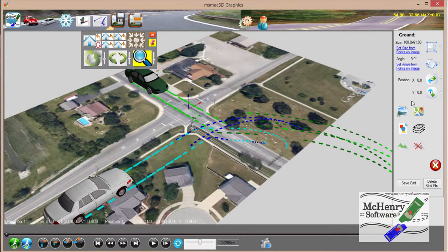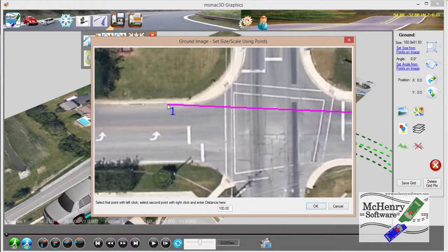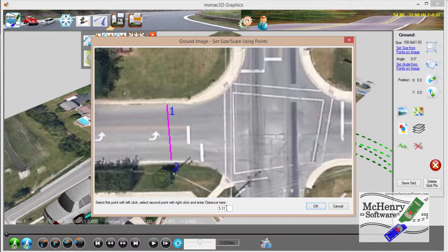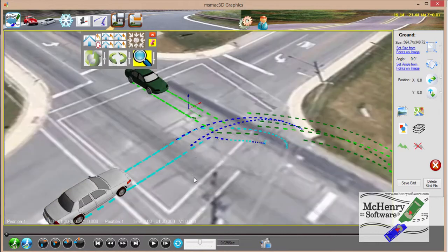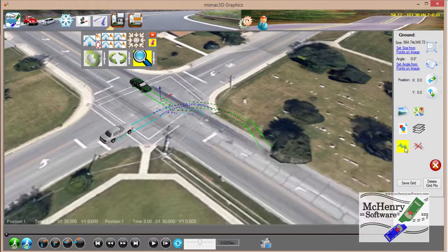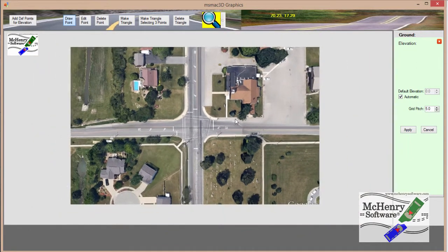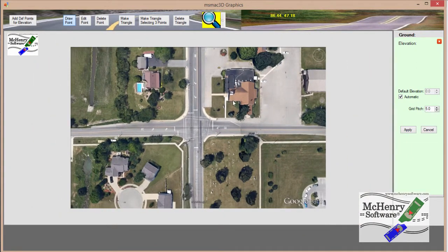But what we're going to do is go ahead and set points from the image. Set this at 30 feet. Now we're going to go down here. This edit elevation and or remove elevations. We're going to have the edit elevations. Normally I zoom out so I can see the whole plane because you want to do most of them. It defaults to draw a point. So we're going to put some points along the edge of the road here.